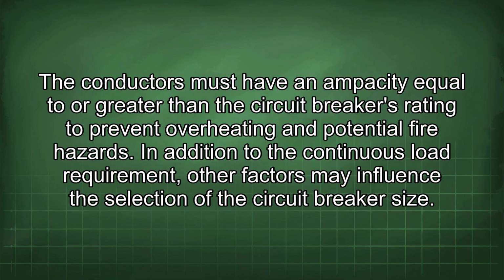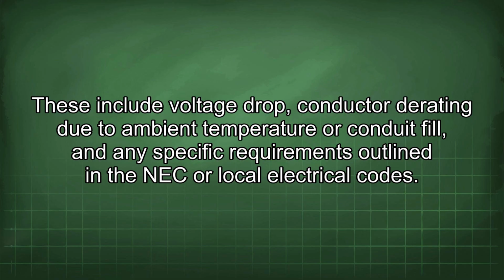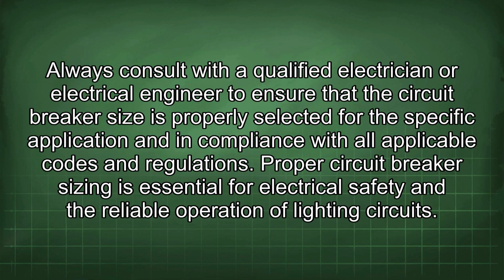fire hazards. In addition to the continuous load requirement, other factors may influence the selection of the circuit breaker size. These include voltage drop, conductor rating due to ambient temperature or conduit fill, and any specific requirements outlined in the NEC or local electrical codes. Always consult with a qualified electrician or electrical engineer to ensure that the circuit breaker size is properly selected for the specific application and in compliance with all applicable codes and regulations.